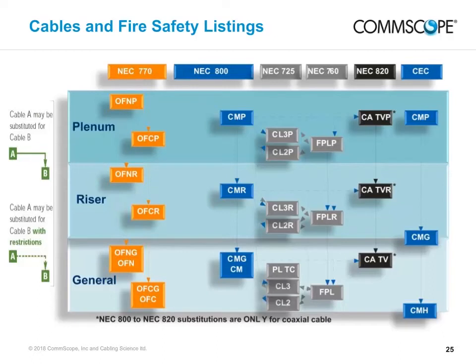Fire safety is as important as cable performance. This chart shows cable ratings or listings for appropriate sections of the U.S. National Electrical Code, NEC, and the Canadian Electrical Code, CEC. Plenum cables are listed for use in plenum spaces. Riser cables are used in building risers, raceways, and trays.